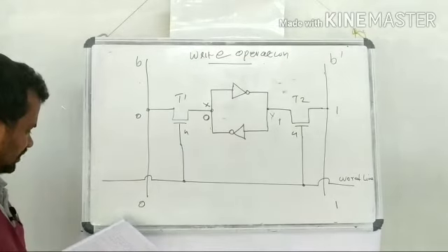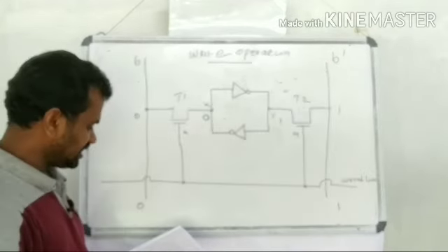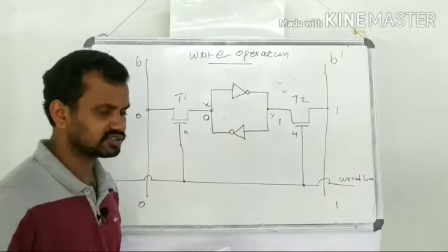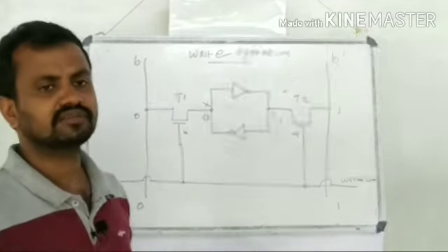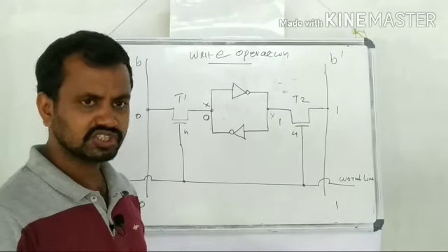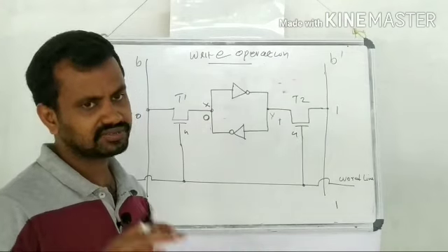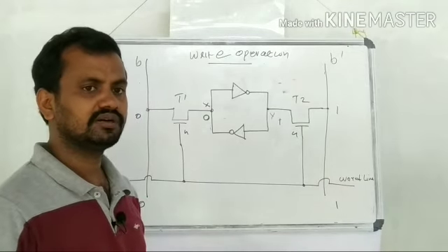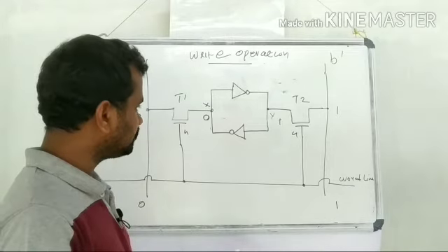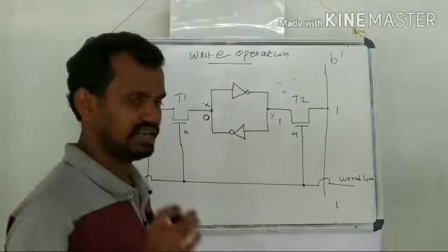And the required signals on the bit lines are generated by the sense/write circuit, because the value actually to be written is received through the data lines, that will reach into the sense/write circuit, and then the sense/write circuit will set the bit lines to the corresponding values.